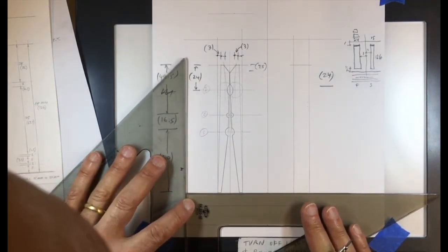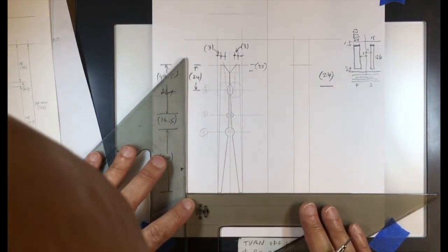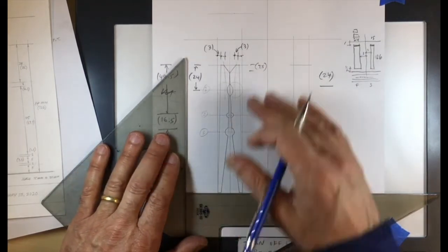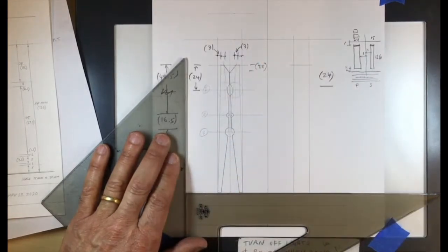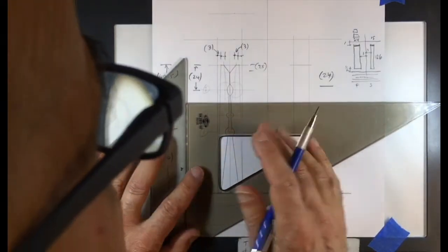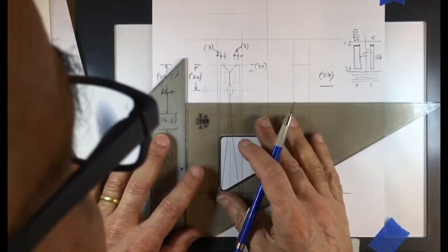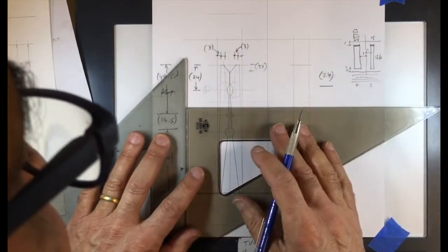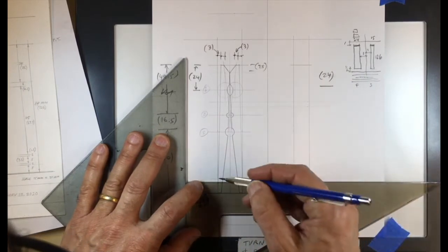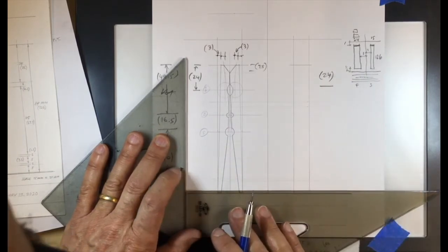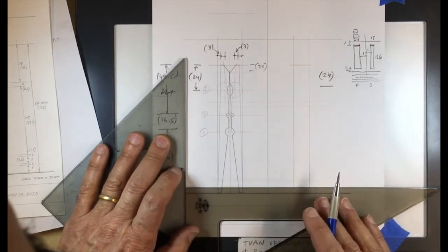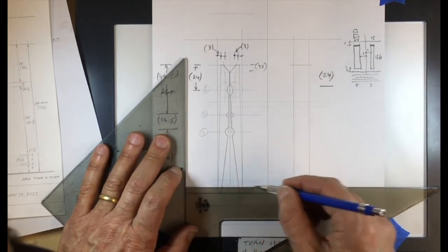Again, don't forget, don't use two triangles like I'm using to do all your horizontals because you already have your gadget, right? You already have this thing that goes up and down. You don't need to do what I'm doing. So light lines, just like that, just to see what you need to then highlight further later. I missed there, a little too thin. I'll have to keep track. I did a double line there that I didn't need.